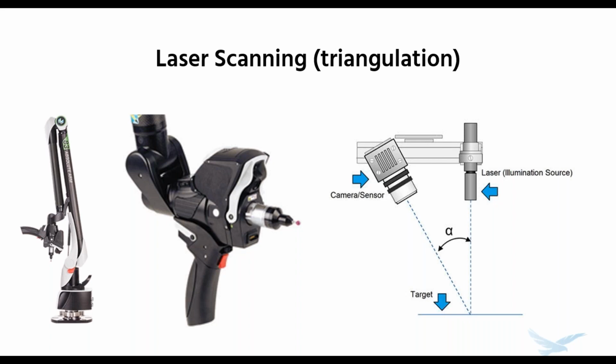And this makes them a really good choice for a lot of applications like scanning thin parts like sheet metal, and the touch probe can trace outlines and cutouts instead of you having to try to scan those really thin edges. And it can also capture areas not outwardly visible with the probe. It can collect measurements on the fly with the probe, rather than processing scan data and taking measurements off that. So these are a longtime favorite in quality assurance.